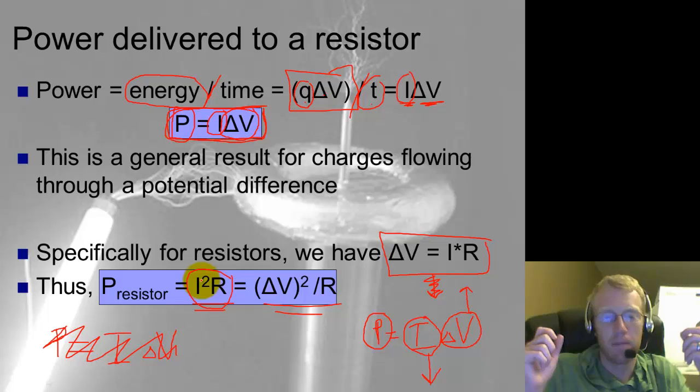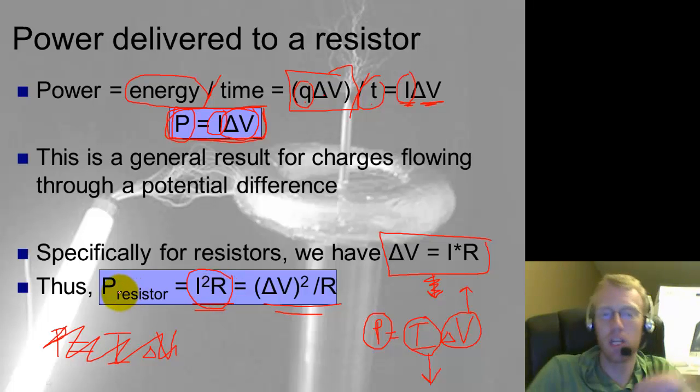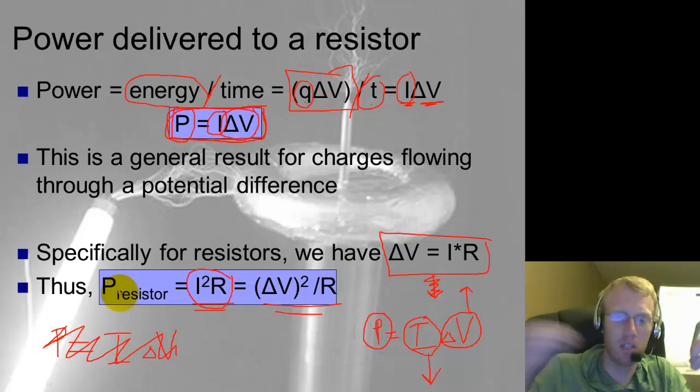And so, if you had a big thick metal cable that's a few feet long, its resistance would be negligible. But when you have it 10 miles long going from the power plant to your house, then suddenly that resistance becomes really important. And if you had a lot of current traveling through that resistance in the wire itself, you would lose a lot of energy just getting from the power plant to your house.